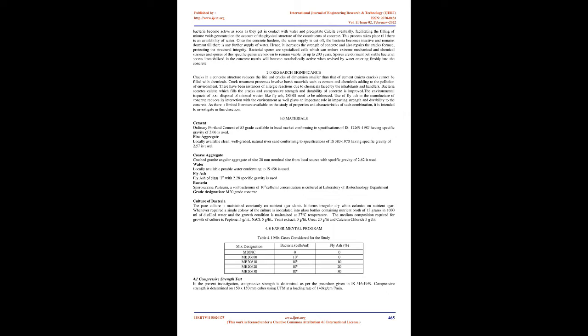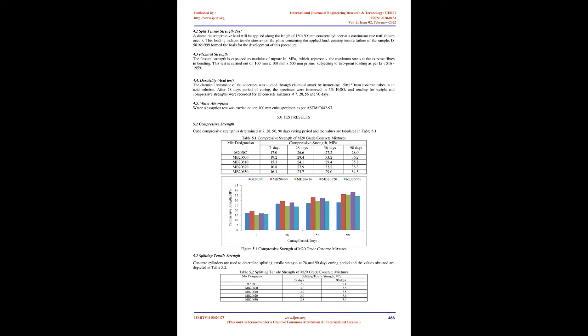If a concrete is developed that can repair the cracks automatically, self-healing, it would save time and money both on the cost of injection fluids for cracks and also on the extra steel that is used in structures only to limit crack widths. For structural reasons, this extra steel has no meaning. A reliable self-healing method for concrete would lead to a new way of designing durable concrete structures, which is beneficial for the national and global economy. In both developed and developing countries, recent researchers are aiming at energy conservation in the cement and concrete industry, focused on the use of less energy-intensive materials such as fly ash, slag and natural pozzolanas.